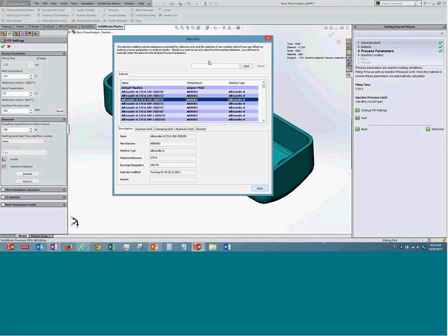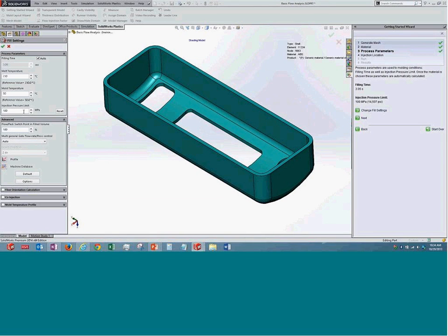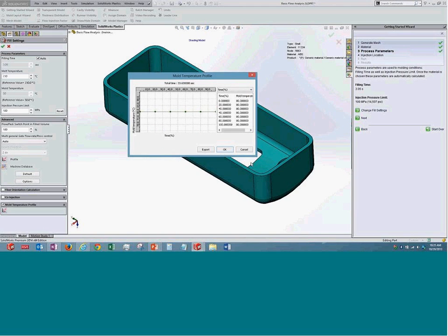A few small options which I will just show you but not use in this example. One is fiber orientation calculation. So if it has to be calculated, you can do it. It's telling you what is the percentage or volume of those fibers. Second material, if you are going to have a second material and inject it, you can give those details here. Mold temperature profile. Mold need not be maintained at a single temperature. You can play with the temperature variation, and at the time the temperatures can be different, and we can give you that variation of temperature over here.